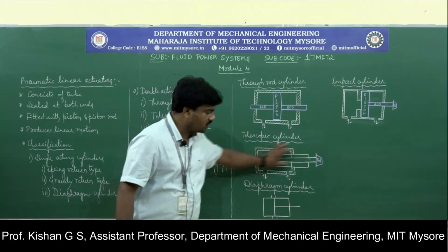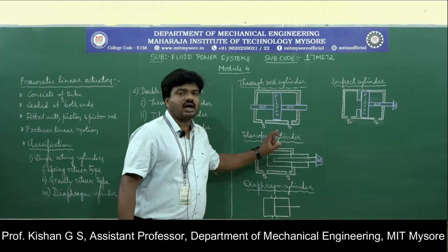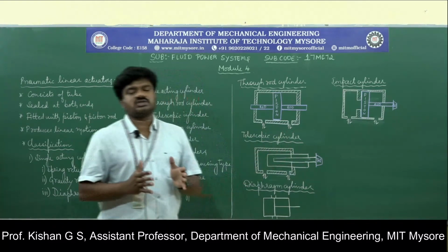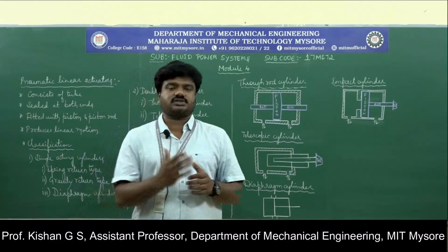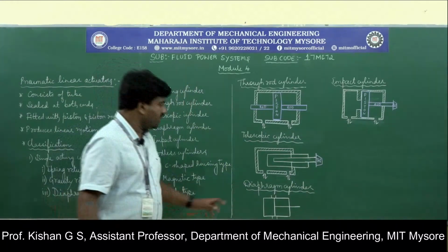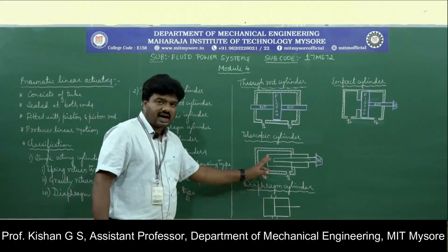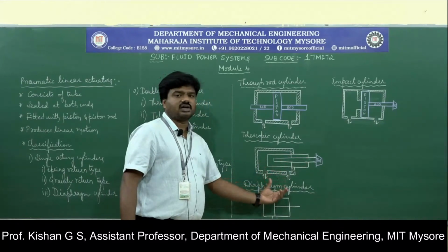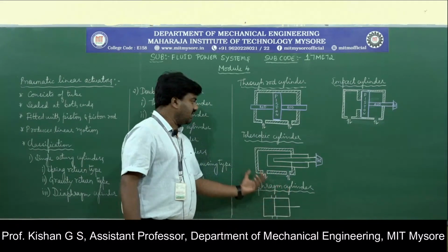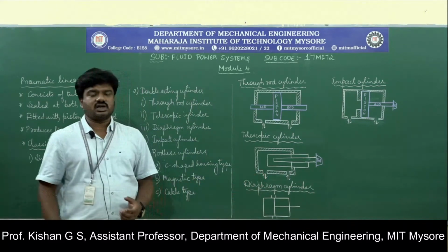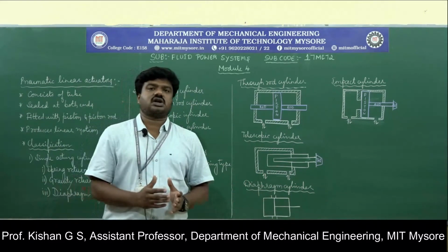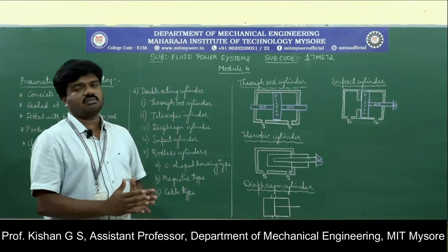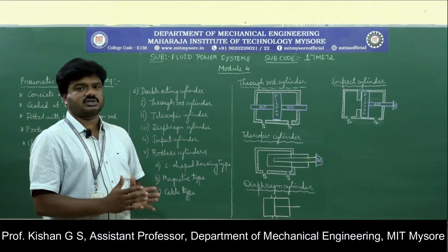The first tube opens, next comes the second tube, and so on. The sequence of opening for a particular extension will be controlled by the compressed air, as well as the retraction of the same will also be taken care of by the compressed air. Hence it becomes the telescopic type of cylinder. Again here both extension and retraction will be from the same control of compressed gas.